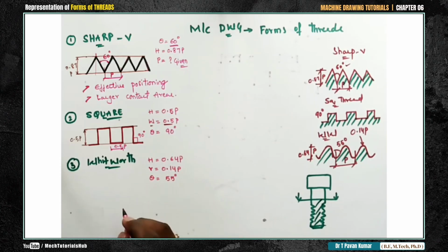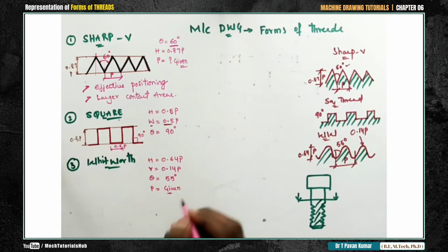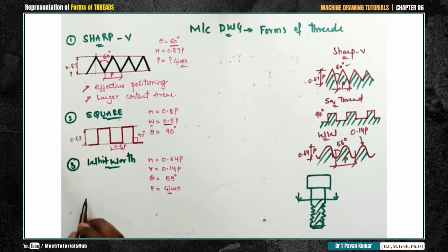Now at some offset distance of p, whatever the given value, make a mark of p or p by 2. From here, maybe this is p up till here, p. Again apply the same principle, r value. From here make a mark, draw a semicircle with 2H pencil. Everything till here has to be done with 2H pencil only. Finally when you draw the profile, draw with HB pencil.